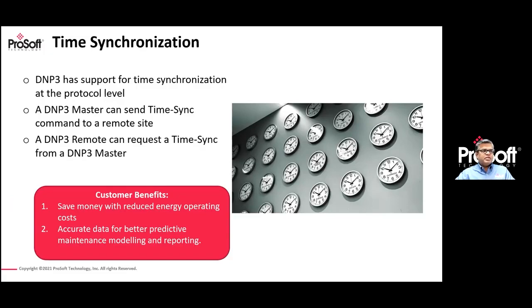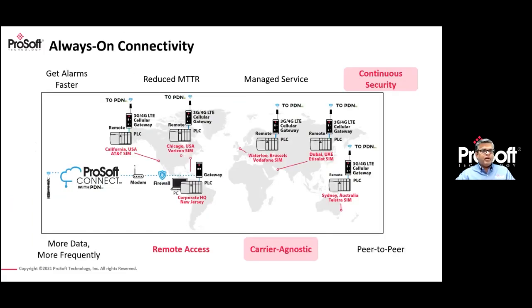Remember at the very start, I mentioned that to address the data reliability and data integrity issues for utilities where all of their assets are remotely geographically dispersed, the solution is going to be in two steps. The first part was DNP3 with all of its features, where it addresses that reliability issue. The second part is, now that you've addressed that and you've got the accurate data, you want to bring that back on to the master.